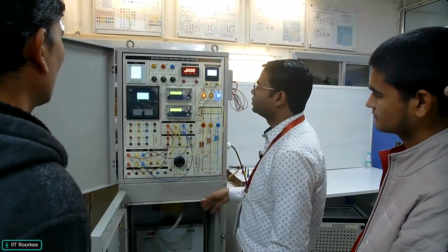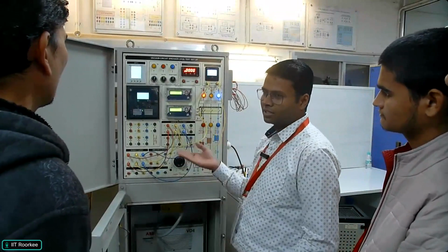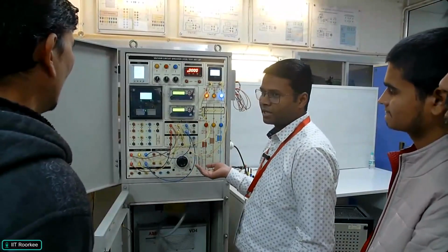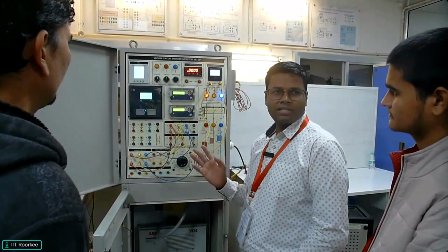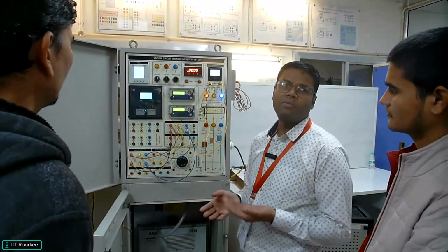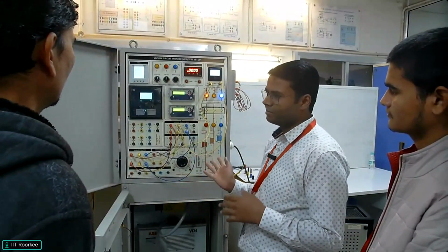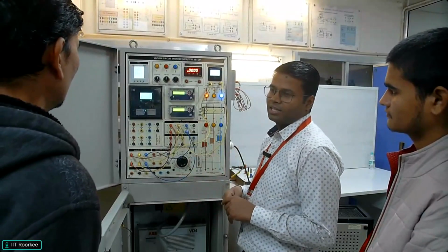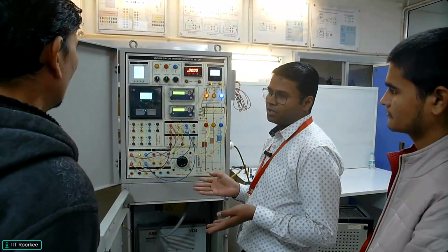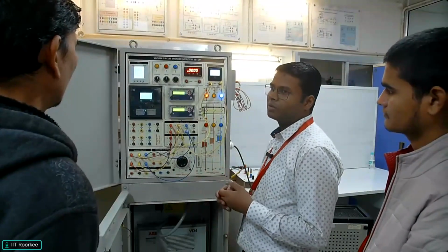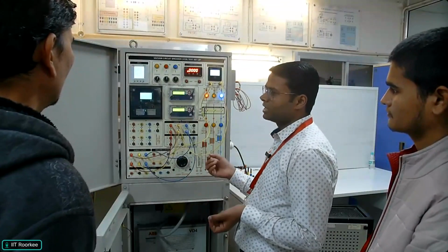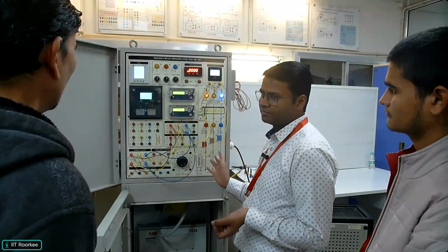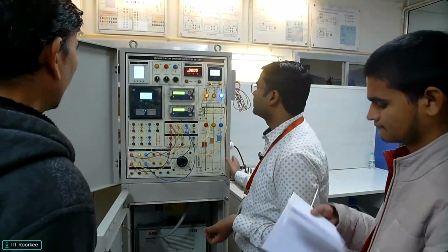So the use of a vacuum circuit breaker compared to some other high voltage circuit breakers like the oil circuit breaker, air circuit breaker, and SF6. All of these depend on the different medium, how we are quenching the arc with the different medium. There is some advantage of the vacuum circuit breaker, like fast operation compared to others, because if you see medium wise, the dielectric strength is more compared to other media. So here we have an 11 kilovolt breaker.